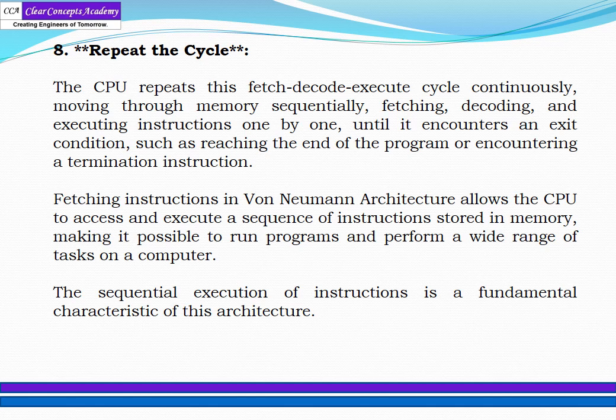In Von Neumann architecture, sequential operation is the fundamental characteristic. These do sequential operation one after another. Whereas in the case of Harvard architecture, there is a parallel operation. Instruction and data are brought simultaneously. That is not happening in this case, because the instruction is brought, and whatever that instruction is telling, that data will be brought.